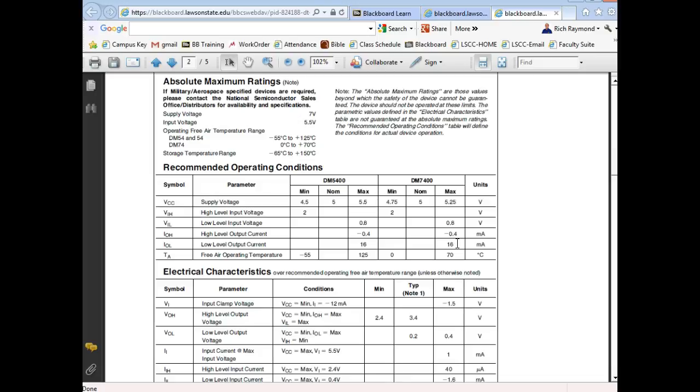Yeah, but you're not going to run into that much anymore. Predominantly, it's going to be the same logic, but it all depends on what speed and what power you need. So S is still in TTL. By the way, the S series is the fastest guy we got, but it consumes more power. It's got a propagation delay of like 3 nanoseconds. Standard TTL is 10 nanoseconds. LS is around 10 nanoseconds. LS is around 9.